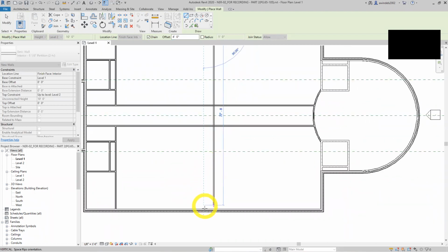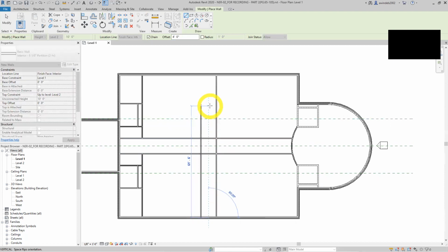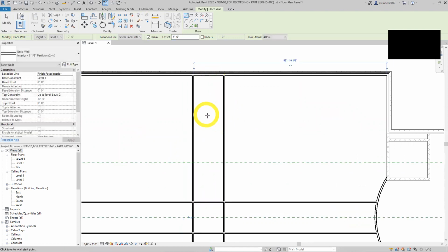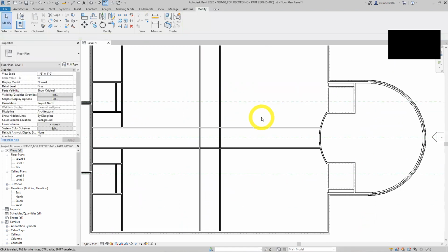I'm going to go down, go to the middle of this wall, the O snap triangle, midpoint again, leave the command running, don't escape from it. Because we know we want to build this wall back, keep it going when you can, if you know you want to continue your building. Now I'm done. 4 feet, 4 feet, escape twice.